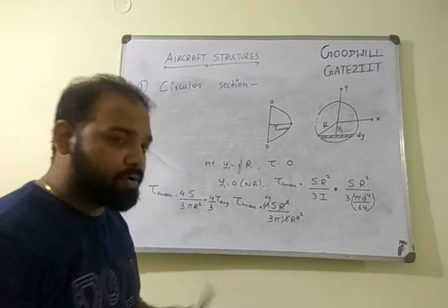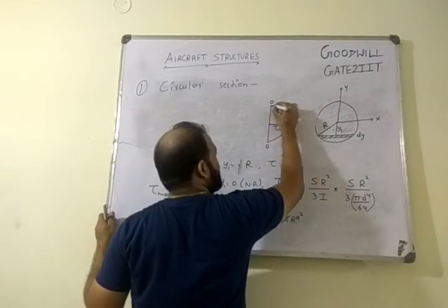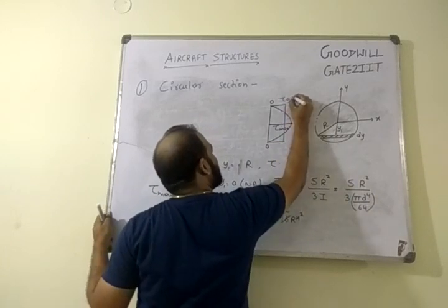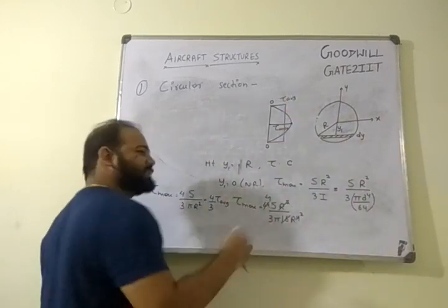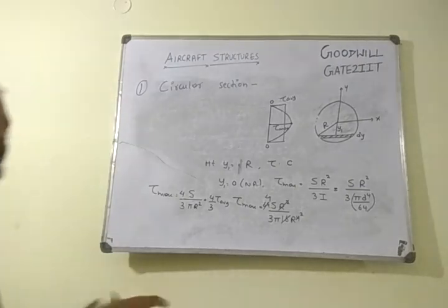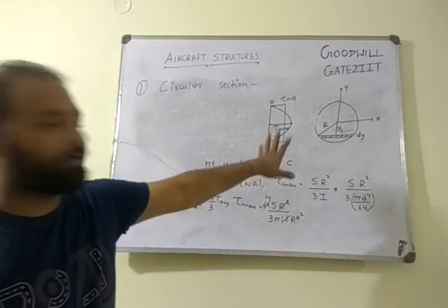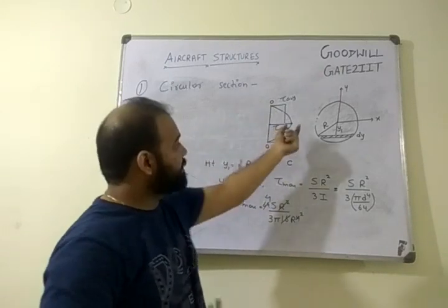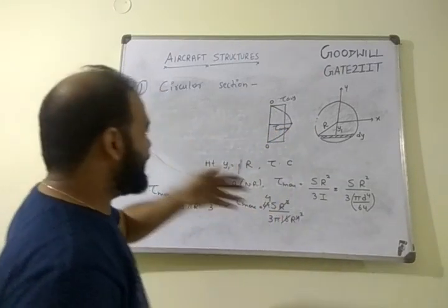And if we don't go by this formulation, the basic strength of materials approach, then everywhere it is tau average. We don't bother about whether we are at neutral axis or outside, just average, force by area. Everywhere it is force by area. Now we are saying that is not correct. The actual values are, you're over predicting here and you're under predicting here, under predicting by 33%. So it is bad.